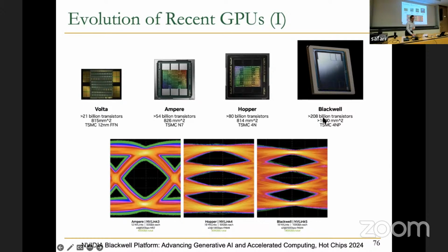But also don't underestimate the interconnect. So these latest GPUs have a small amount of memory. They figured out that you needed high bandwidth memory to access large amounts of training data or inference data. But this high bandwidth memory cannot be built with very large capacity because it's 3D stacked, etc. And there are a lot of issues which we may discuss also.